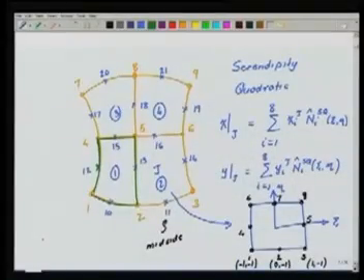It need not always be isoparametric. For example, if I'm using 8th order approximation, I need not use an 8th order map, but we have to use some sufficiently higher order map. It could be subparametric, or it could be isoparametric. If my p is equal to 2 for the approximation, p equal to 2 here will do the job. So that is the idea, that each geometry has to be controlled. And you see here something curious, that in doing what we have done, we have ensured that the mapping is continuous.